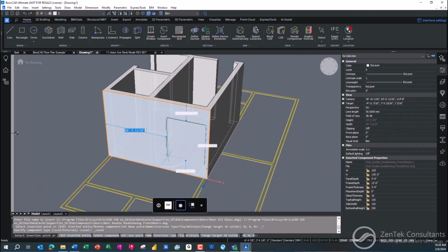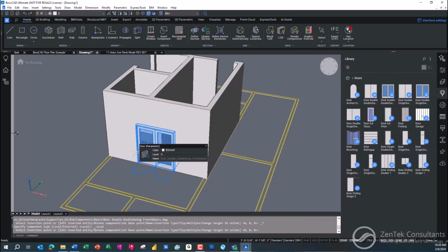You see, all I got to do is just drag it over here onto the wall. And you see it'll turn itself to whichever wall I'm on. Right, it'll rotate itself. So in this wall, what's great is I can use the tab key. See the dimensions? I can just use the tab key to set the dimensions. So I want it 0 on the bottom, so it's flush. All right, and you see here, I can go ahead and say I got 5'3" on the left and 5'6" on the side. Let's say I'm going to put this at 5'4" from that corner. And just like that, it just puts in your door.